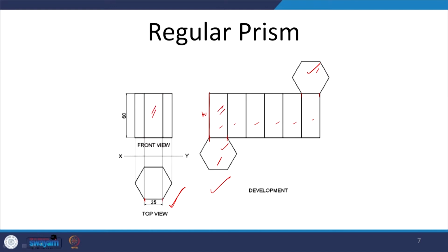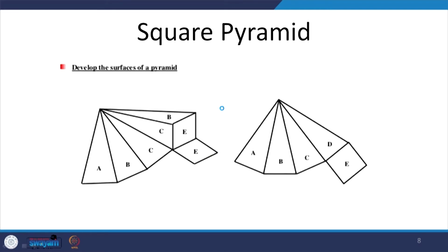So it is going to be equal to the same surface, which is the true shape. So every time we draw the surface, it is drawing the true shape of each face and putting all of them together. So we are just making all these true shapes of the faces of a solid continuously, such that they are all joined to form a proper solid shape.